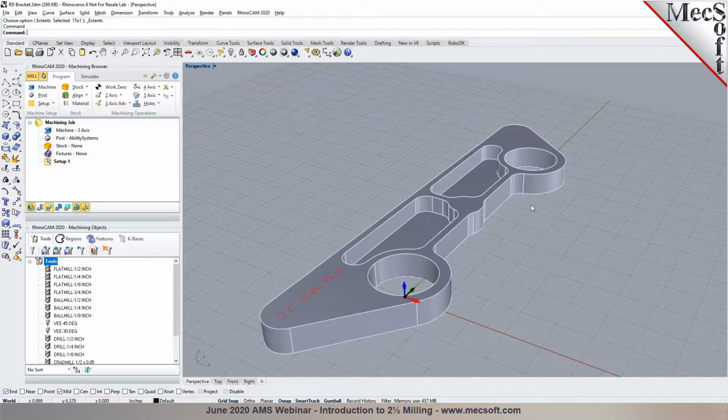So consider like you have a bunch of curves or sketches with a straight extrusion. Those parts can be programmed using 2-axis or 2.5-axis. In the case of 2-axis or 2.5-axis, your tool or the cutter maintains a constant Z as you're moving in X and Y. That's why it's called 2-axis, where the X and Y keep moving and your Z remains at a constant depth.